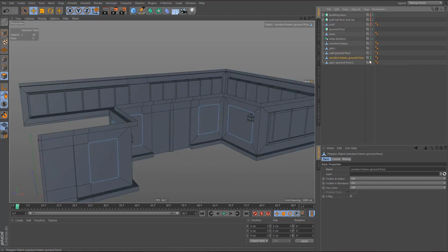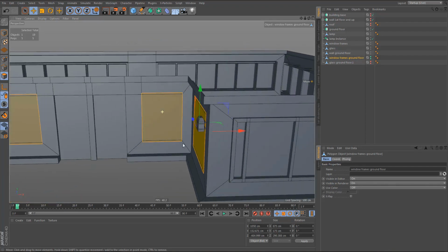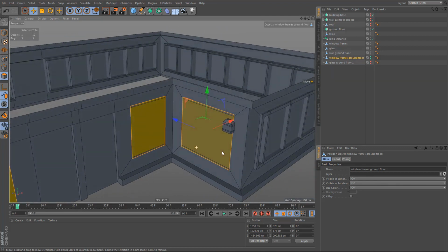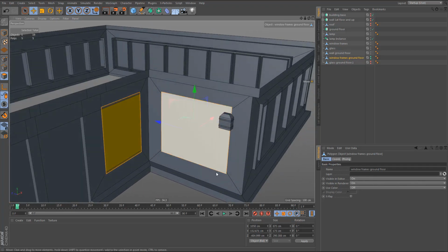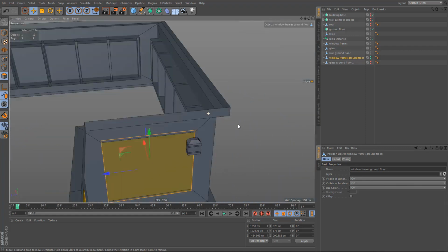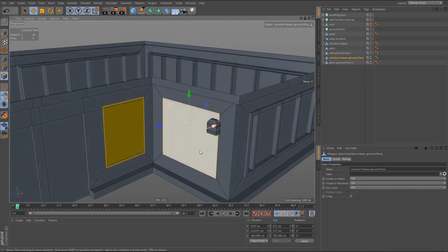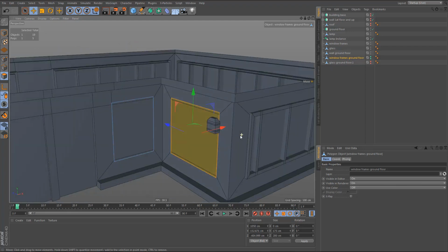And as for the window frames, I'll select all of these and I'll change the size to 175, which is what we did for the other window frames. And I think we don't need to change the width, although we could. We could have done this for the window frames on the rest of the object as well. That's just so that the window frame sits on the geometry of the wall. And I didn't do that for these window frames. These are flush with the opening. Shouldn't be a problem, but could be a problem when you render with GI, because we don't have any geometry going inside on this wall, and sometimes that causes issues when you render with global illumination.